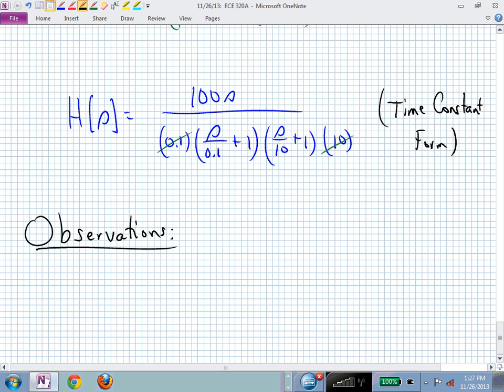Just based on that transfer function, can you tell me? Now what you're keying in on are poles and zeros at the origin. If you have no poles and zeros at the origin, if you just have linear and quadratic factors, your slope at low enough frequency should be 0. In this particular case, what do you have?